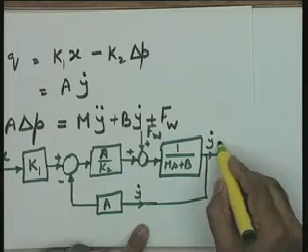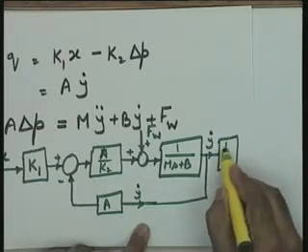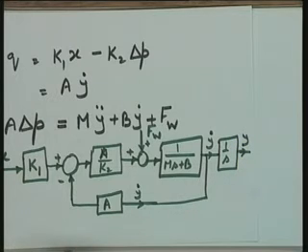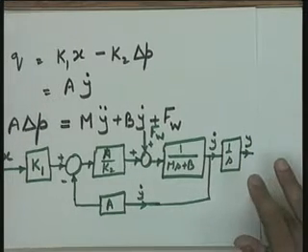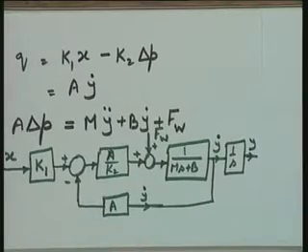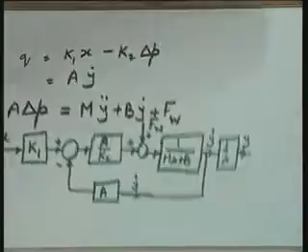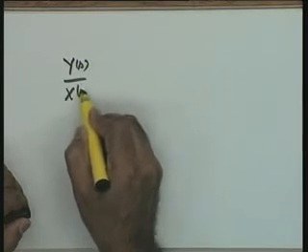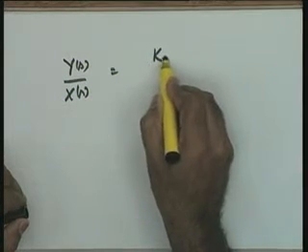Now this y dot, as we have been doing earlier, this is 1 over s here, and the displacement y is available to you. This is the total picture, and if you take the transfer function model for this particular system, the transfer function model between y and x is of this form in terms of parameters.